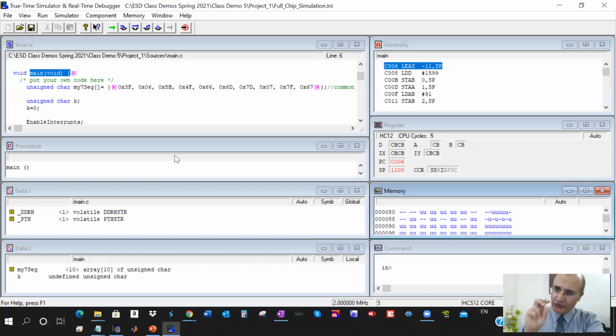It took the code from Flash, but when I ran it from here, this development environment added some piece of code to configure the PLL clock, to make it faster. Yes, the code was there, but setting the clock speed was done by this development environment. That's why I flipped to run mode and ran completely from there without CodeWarrior, and the clock was slower because this piece is not in the flash memory. We're going to write it later on our own in the flash memory.